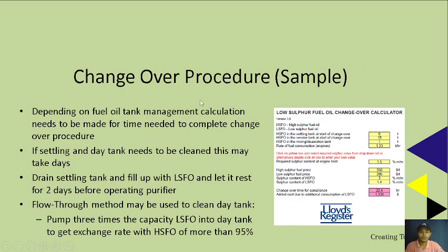So, changeover procedure. Depending on fuel oil tank management, a calculation needs to be made for the time needed to complete the changeover procedure. If the settling and day tanks need to be cleaned, this may take days. So drain the settling tank and fill it up with low sulfur fuel oil and let it rest for 2 days before operating the purifier. The flow-through method may be used to clean the day tank. So pump 3 times the capacity of LSFO into the day tank to get an exchange rate with HSFO of more than 95%.